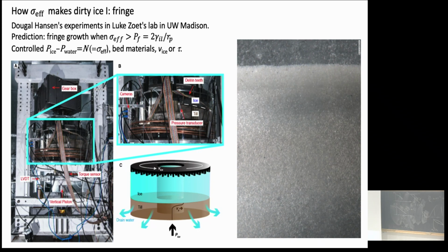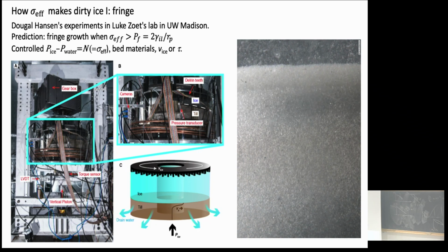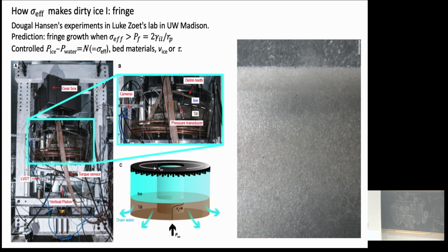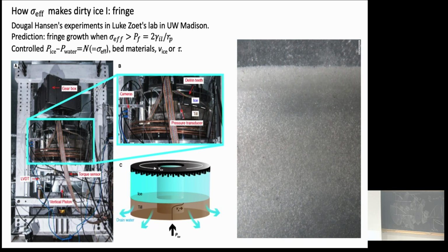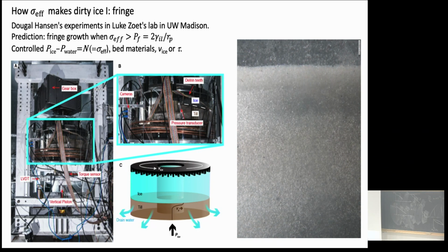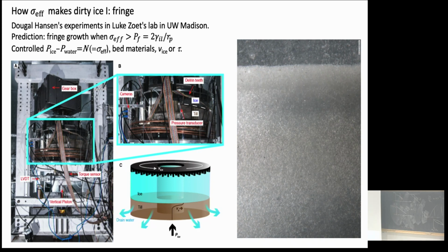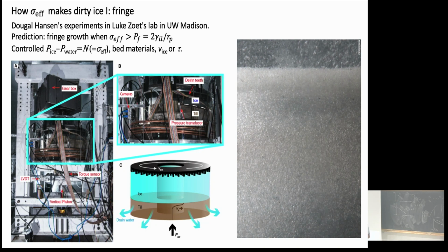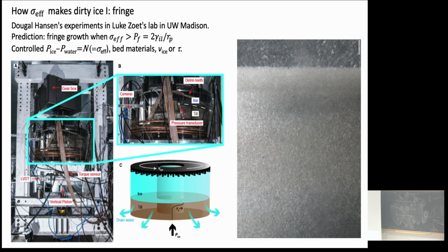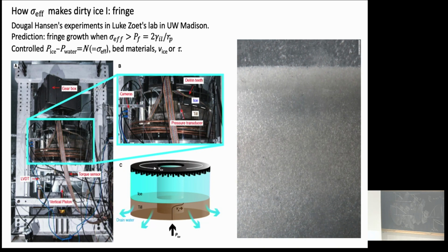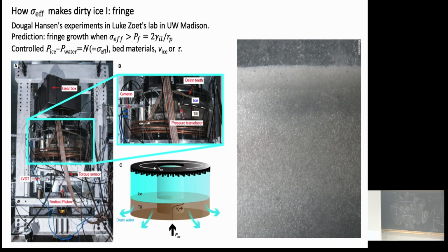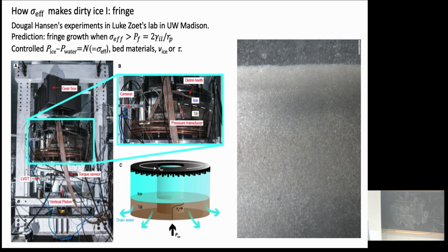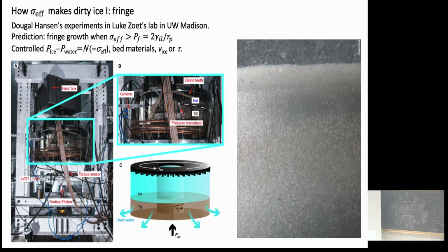The beads start out saturated with water, with deionized water. So it's starting off as a wet porous medium, ice on top, and we start it going, after applying a normal stress with a ram, allowing water to drain out through the bottom and measuring the water pressure as well so that we can calculate the effective stress. But in this experiment, it's meant to be as simple as possible.